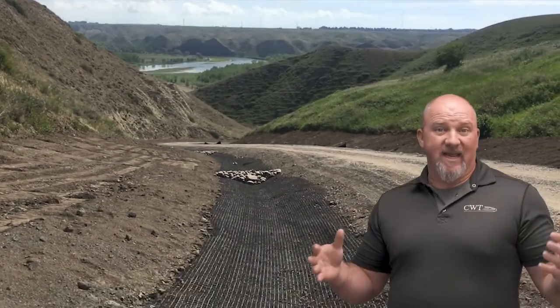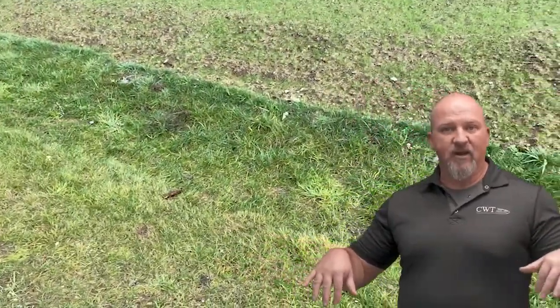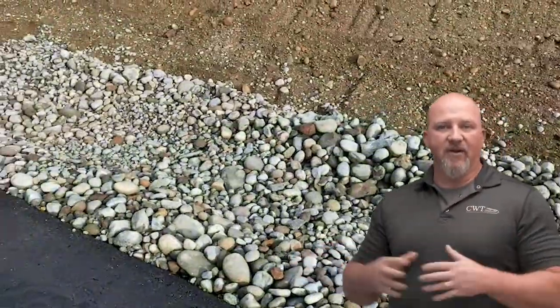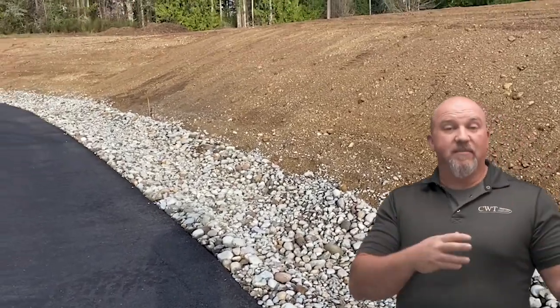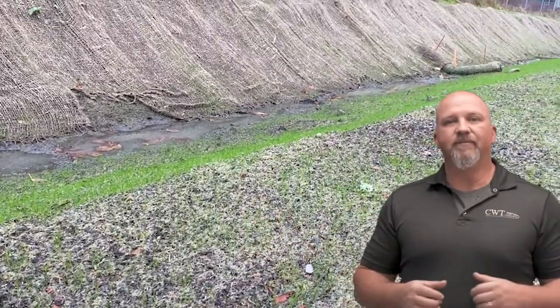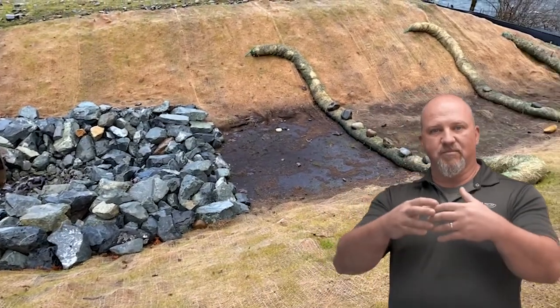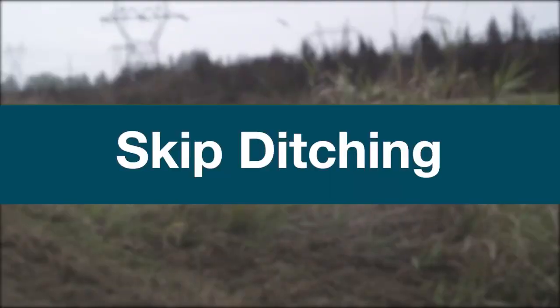You might use a permanent installation like a TRM that's going to be left there in perpetuity, or you may use something like a sod or rock liner so you're not adding velocity to the sediment and sediment's not being transported or picked up by the channel itself in that flowing environment as you migrate the water down. So structural integrity of your ditch is very important as you're moving water through your property to the downstream environment.